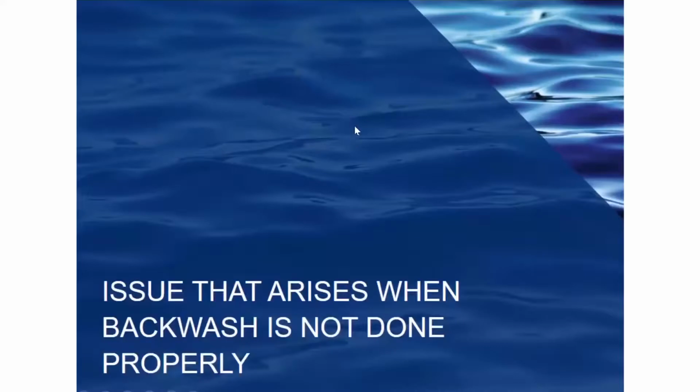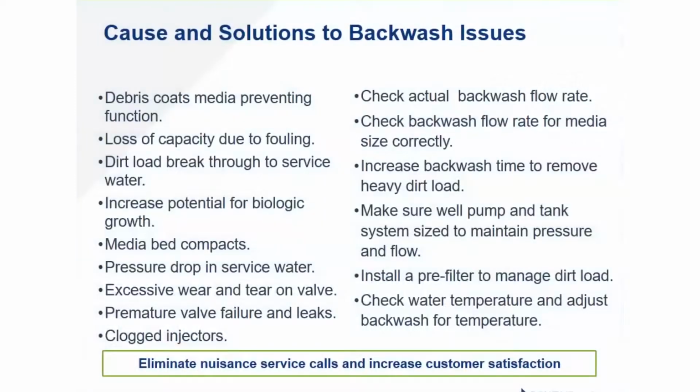So, issues that arise when backwash is not done properly. Debris coats the media, preventing function. You can't get ions to the resin bead. You can't exchange them. Loss of capacity due to this fouling, whether that is particulate or organic. Dirt load will break through to the surface water. So you'll get dirty water coming out of the tank. Eventually, you move the dirt all the way through the tank. You have increased potential for biological growth if this debris is organic in nature.